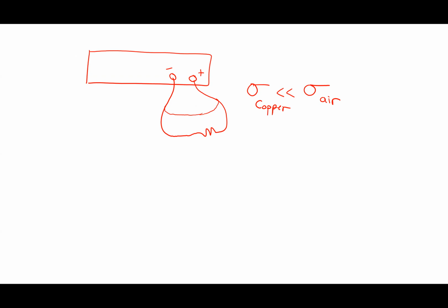You take advantage of that all the time. If that wasn't true, you'd have to do Maxwell's equations every time you analyze a circuit. Every single time, right? It would be a mess. All right, so you don't want to do that, and we don't have to. We make use of electric circuit models where I say V equals IR and all that stuff. V equals IR is an approximation. The reality is that I've got an electric field source and current densities and all sorts of stuff, and I really should do Maxwell's equations, but I don't have to. I can make it an algebraic problem because the charges don't cut through here, and all the charges stay in the circuit.